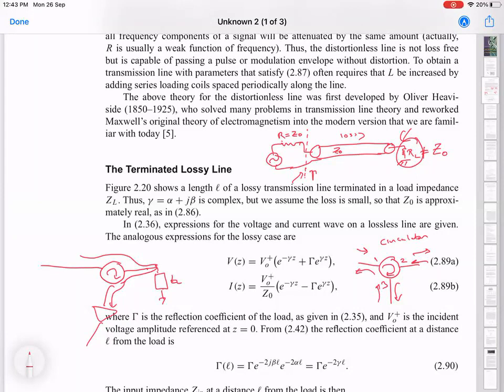And then the signal is actually going through a different path where you can put amplifiers. The same does not work if the signal is coming back in the same way, right? Because you can't have an amplifier going in the reverse direction. So this allows you to separate the incoming and outgoing waves. There is another device called a directional coupler which also does that.